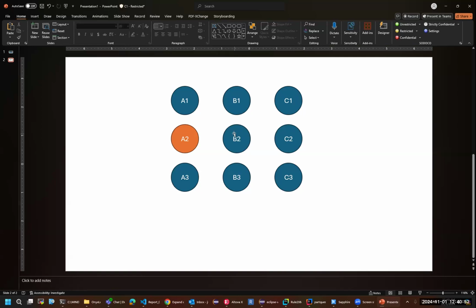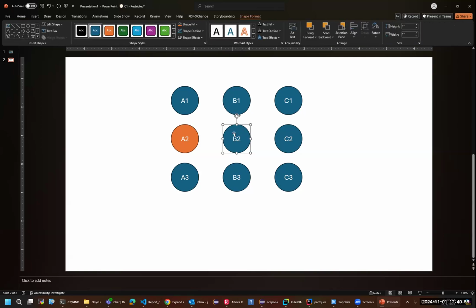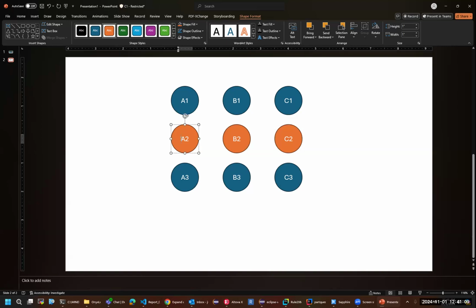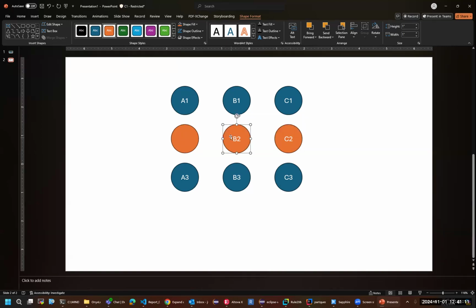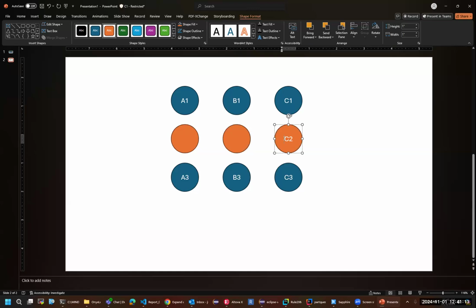It gets a little bit weird with the deleted whenever it comes to a BGA, because for a BGA to have a deleted terminal, that means that the entirety of the row or column has to be deleted. So in this case, these would be blank, and then these would be A2, B2, and C2.